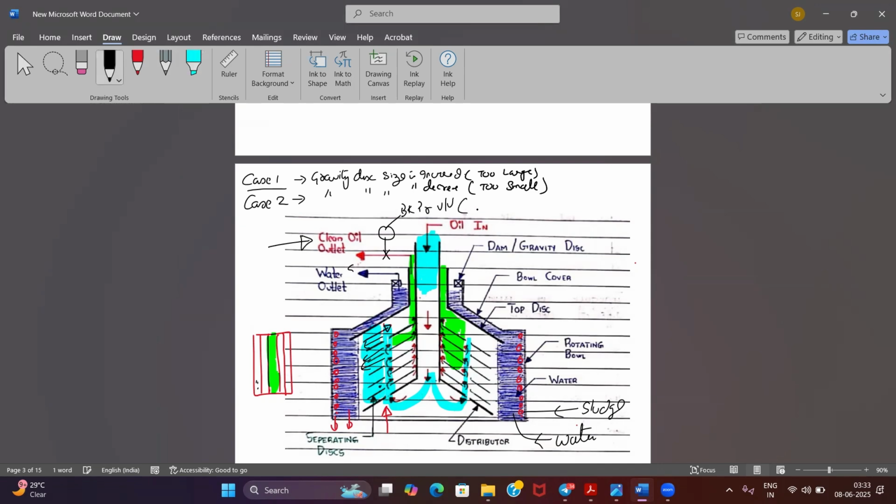Okay, there's a back pressure valve. Normally, the back pressure we maintain is a different value for different purifiers, but in the normal range of 1.5 to 2.2 bar pressure, we have to maintain. This is my pressure gauge, suppose. So this much pressure we are maintaining in my purifier, because I don't want the purifier to act as a pump, right? I want certain back pressure always to be created in my purifier, so that oil can remain for some time, because we saw that separation efficiency will also depend upon time, right?